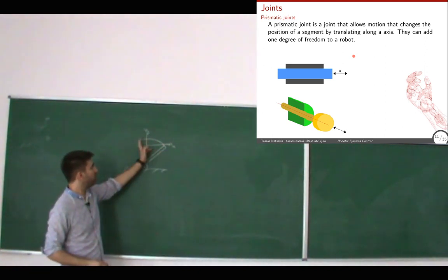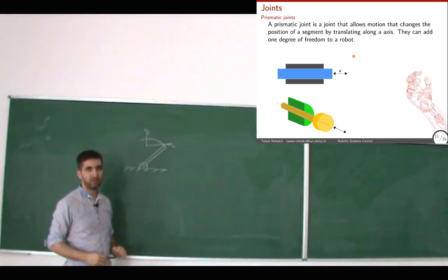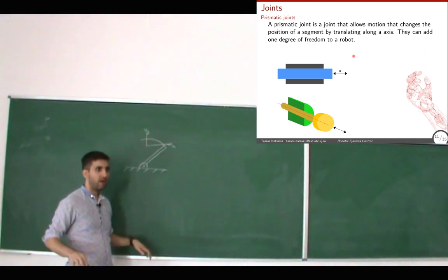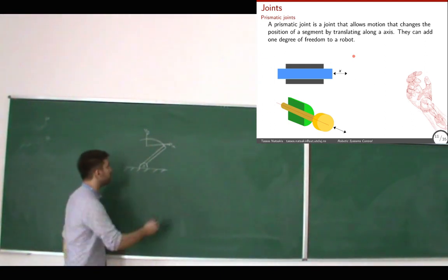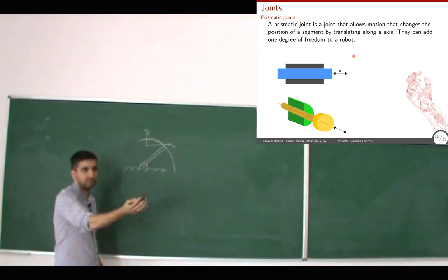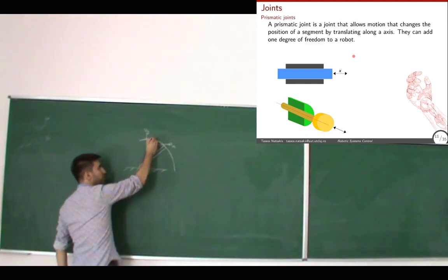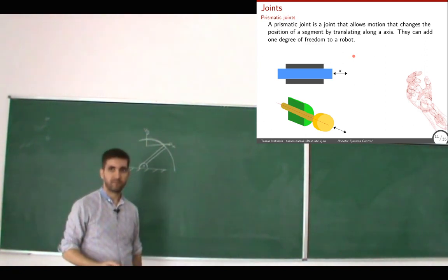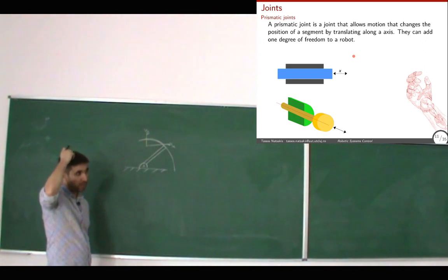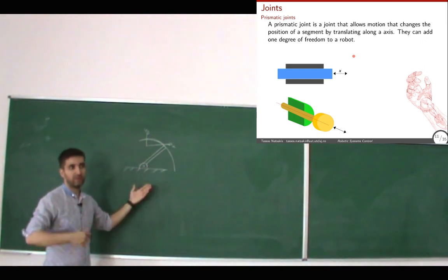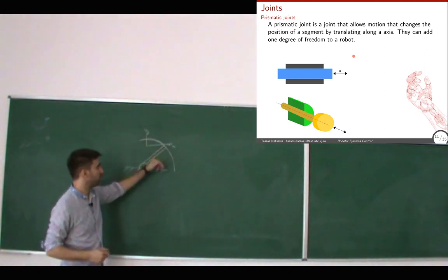Okay. So this robot can move along this plane, let's say, so I can change the 2 coordinates of the end effector, but I cannot change them independently. I cannot change the x coordinate without changing the y at the same time, because this robot will be constrained to follow this circle, this arc. I cannot put it in another different x position, keeping the Y position the same. Okay? Or as you said earlier, I cannot change the position without changing the orientation, for instance. Okay? So that's another degree of freedom that would be there, being able to change the orientation as well.